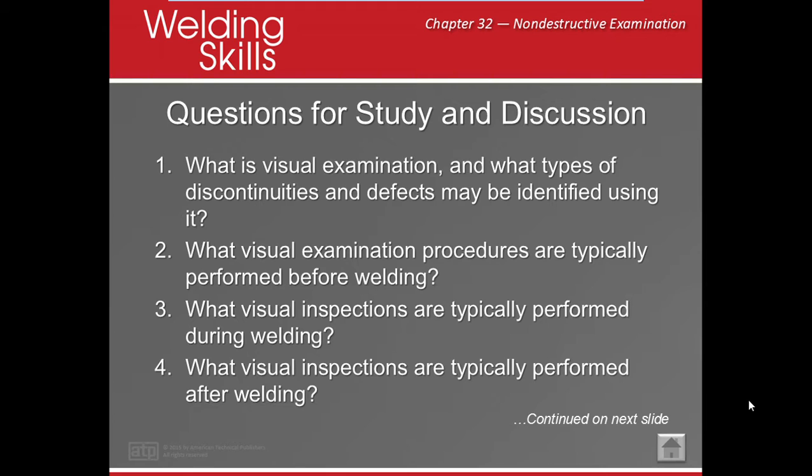And what visual examinations are typically performed after welding? Well, after one would be what? Surface quality, contour, and verifying dimensional accuracy, right? Is there any porosity or undercut that I can see right away?